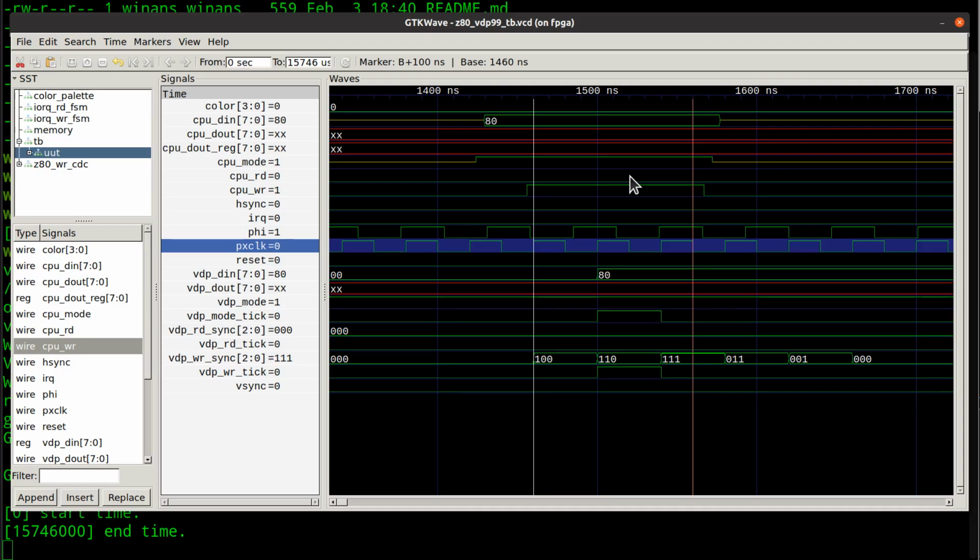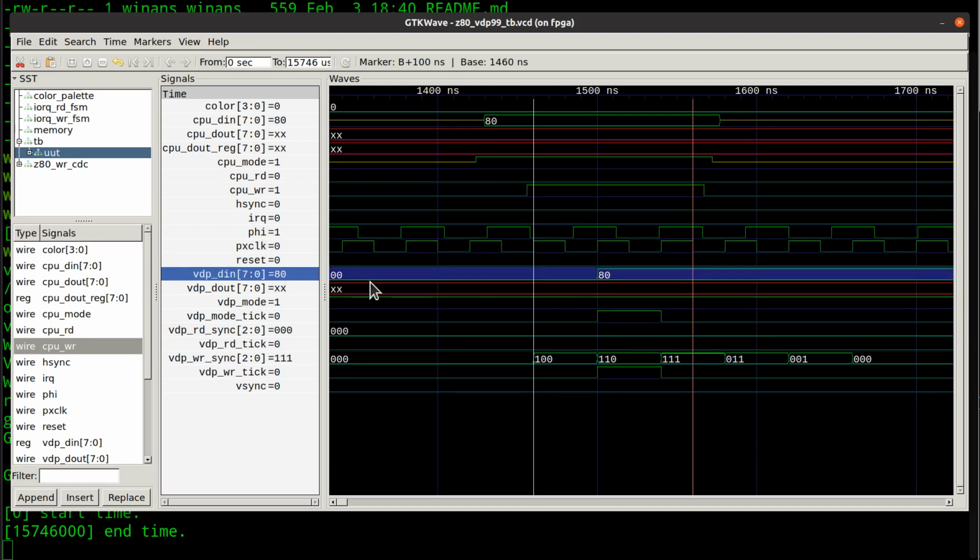However, if you run it and it gets too hot or it's too cold, or as the thing ages, this is going to be the worst case thing you're going to have to put up with. And it'd be nice to know that we can handle that. Worst case being, there won't be enough of these pixel clocks to advance our logic to recognize that what we need is to grab the data off the data bus and store it in one of the registers, okay? So what I've decided to do is, arbitrarily make the decision that it's actually okay, provided that when we grab this, we grab it a little earlier than we normally would.